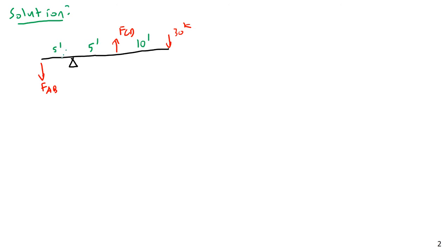And I'm going to assume that this thing is going to rotate about the pin. So we always assume that pins cannot move whatsoever. We're treating them as idealized, infinitely rigid supports. No matter how much force we apply, this will not move at all. So if we apply a vertical load here, this pin will not move downward. It will simply remain as it is, firmly affixed to the ground, and even this rigid beam will simply rotate about the pin.